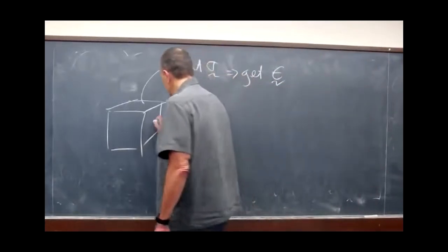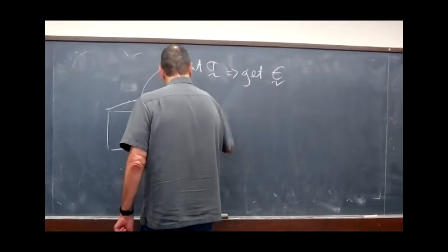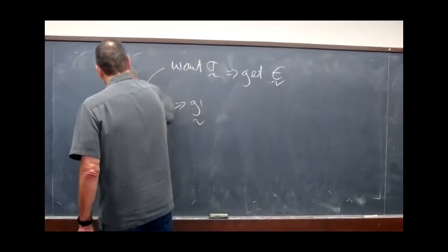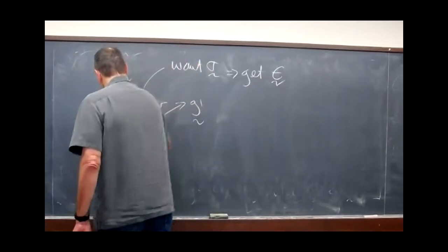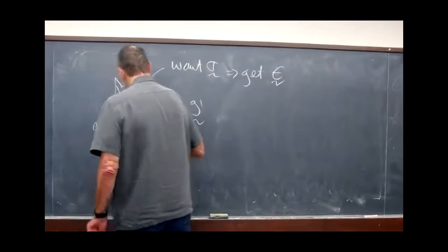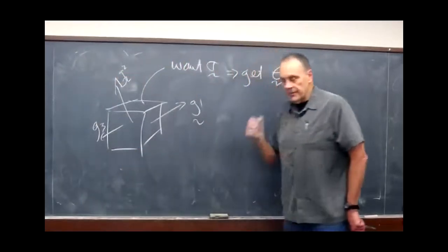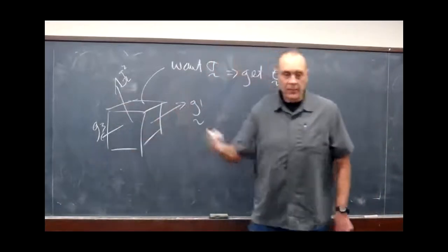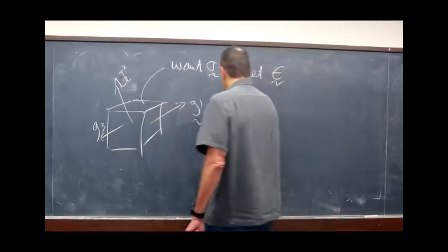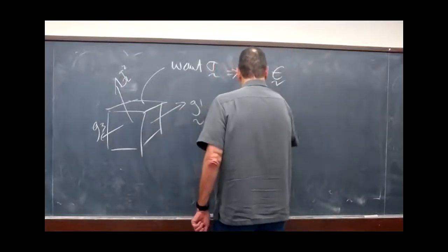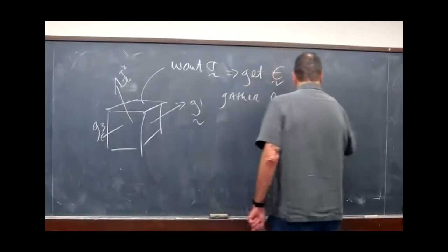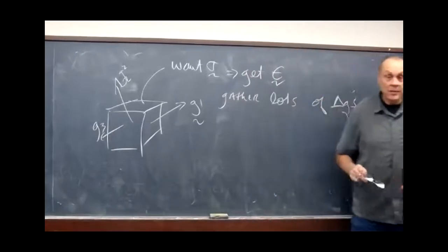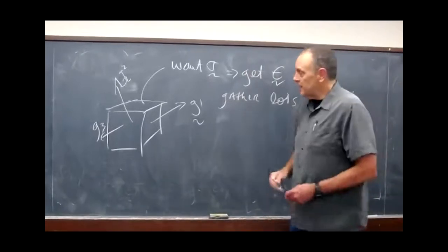I'm going to look at lots of different g vectors: G1, G2, G3. First, I'm going to look at all the spots at one omega, then I'm going to rotate it and look at all the spots at another omega. So I'm going to gather lots of delta G's. It's going to be a before and after, right? But they're not going to be in the plane, right?